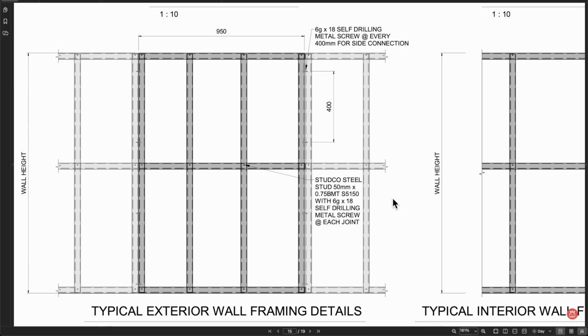So he's defined a 50mm stud, which is actually 51 in stud code terms. So obviously he didn't even read the manual. And then he's got 75 for my interior walls. That probably doesn't make sense to a builder until you understand the structure of the wall that this is going on. It's already framed in steel.